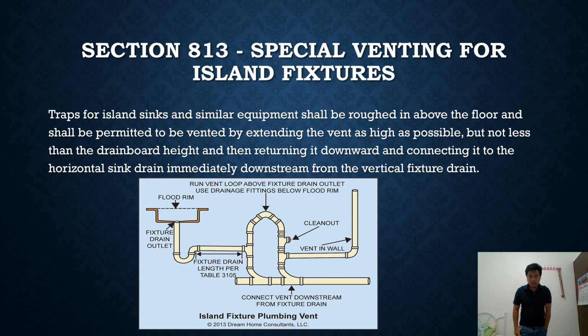That is the example. Run vent loop above the fixture drain outlet. Use drainage fitting below flood rim.